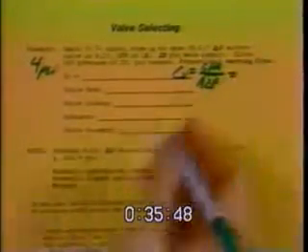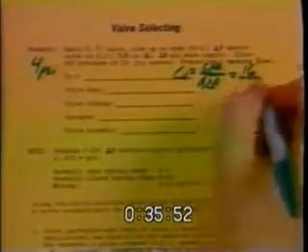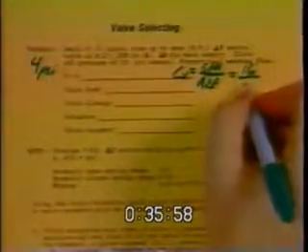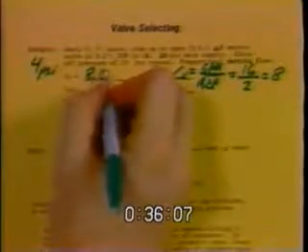In this case, our gallons per minute is 16. Also, I'm already told what my pressure drop across the valve should be. It should be 4. The square root of 4, though, is 2. So our CV comes out to be 8. So I'm looking for a CV of 8.0.